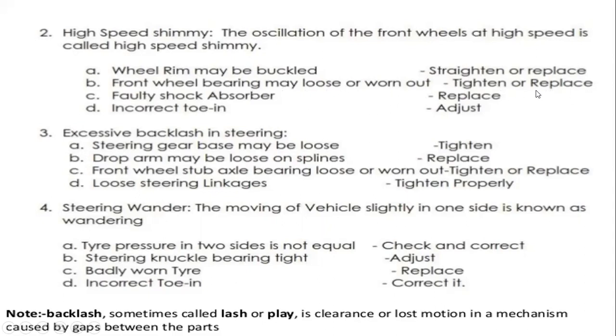So it can be tightened or replaced. Next, faulty shock absorber. The third one is the faulty shock absorber, and it can be replaced. Next, incorrect toeing. So incorrect toeing can be adjusted. So this is for the high speed shimmy.